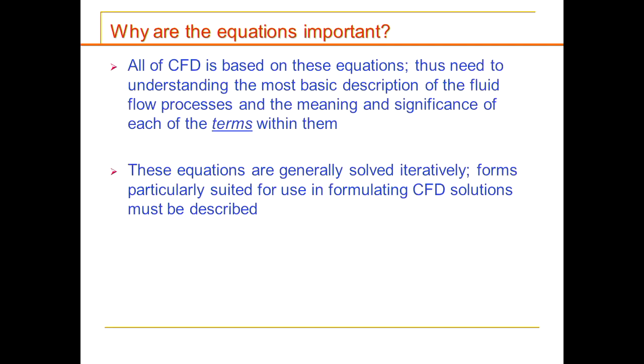That's why you have all the convergence criteria when you start to go to your solver and you see your x, y residue and mass residue goes down while you do the iteration. So the more iteration you do, the more accurate your solution will become. And that's for steady state.